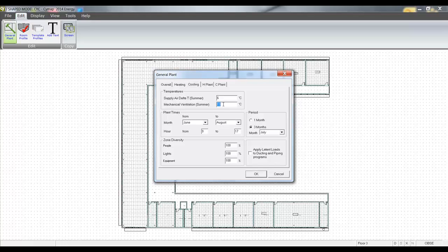Again, if I'm tempering the fresh air for my various months of the year, it looks at the average monthly maximum temperature. We're then chilling that down to say 13 degrees, and again we'll only be looking at the local gains to the spaces when we size our plant within those spaces.